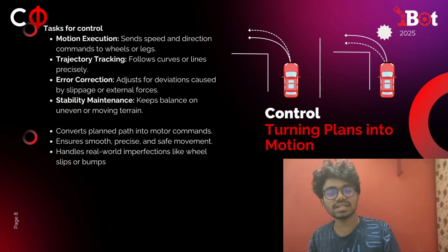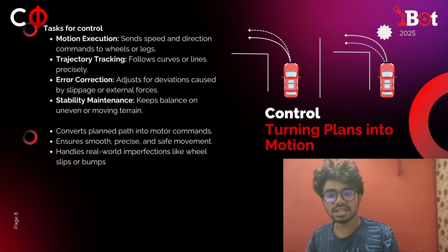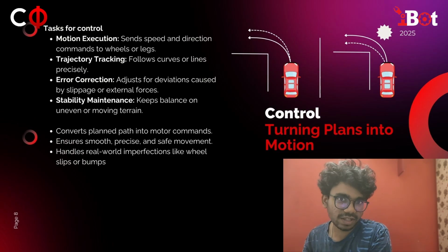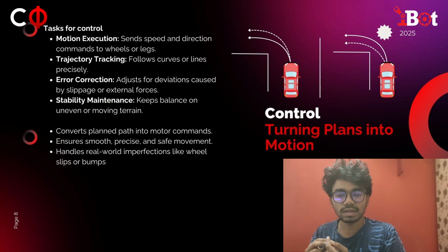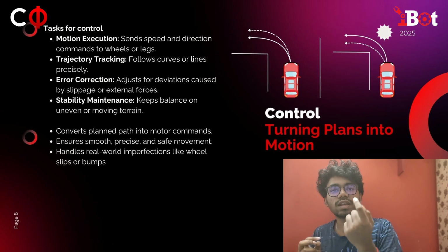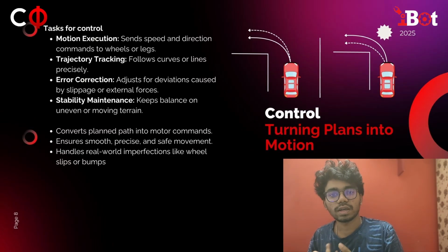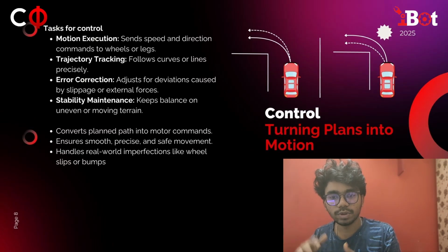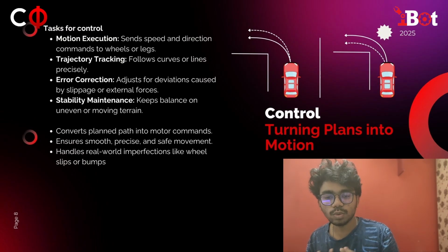This is good, it's very cheap for processing cost, and it gets the job done for a specific maze. For example, I want to solve this specific maze. I just remember turn left, turn right, turn left, turn left, turn left, turn right, and it just reaches this location. This is what we call open loop. We just do it until we get to the destination, and we don't need to do anything else.